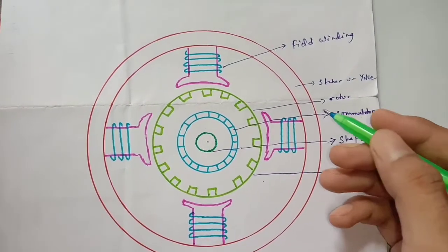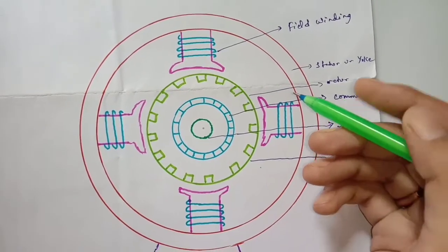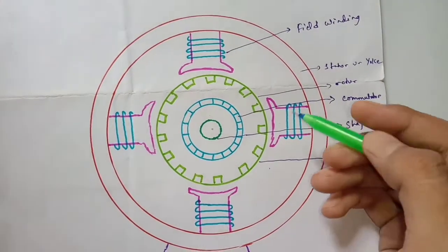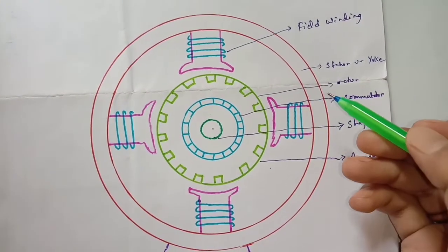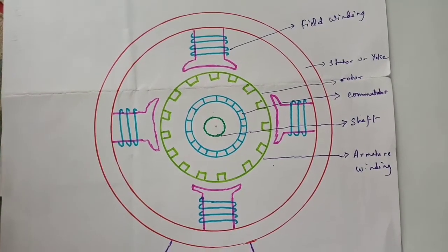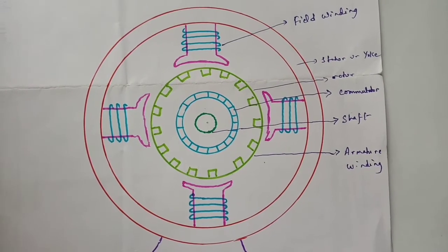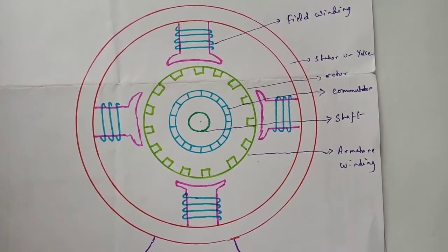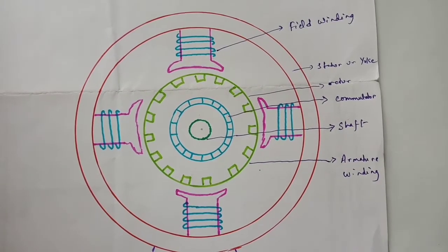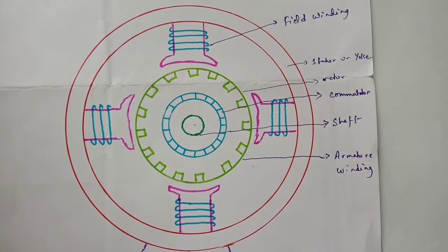This is the construction of a DC machine. The outer part is called the stator or yoke. Actually, the work of the stator is to protect the internal parts, and it also provides support to the pole core and pole shoes. It is made up of cast steel or cast iron, and electromagnet is used in place of permanent magnet